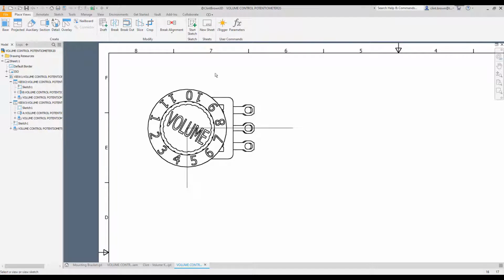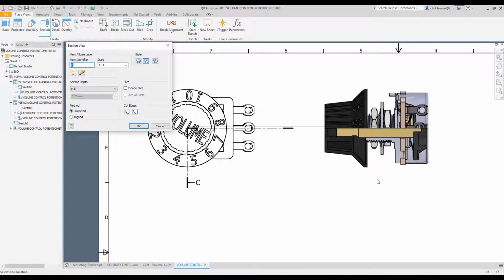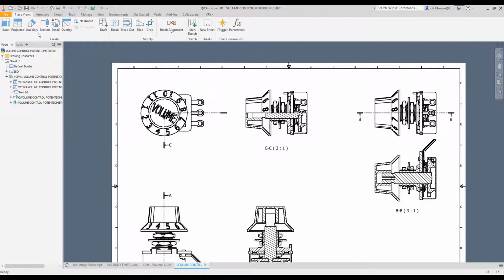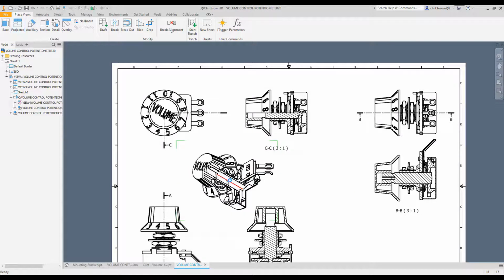Now when I create my section, the section tool actually asks me for some feedback. So normally you select a view. It's also asking for select a view or view sketch. So I'm going to choose my view sketch and I'm going to drag out my view. Right, and the great thing with these quarter sections is that obviously we can project an isometric view directly off of them.